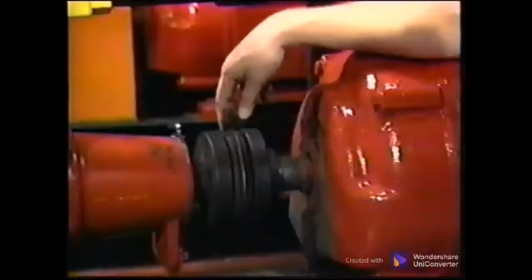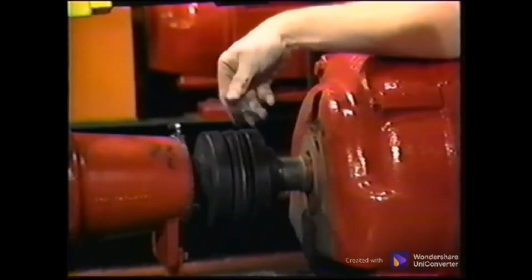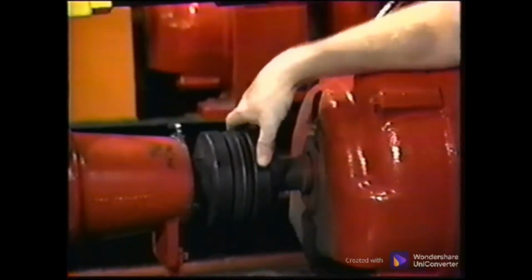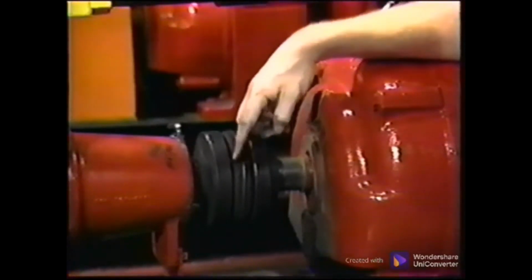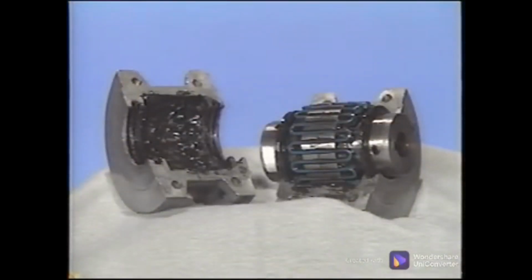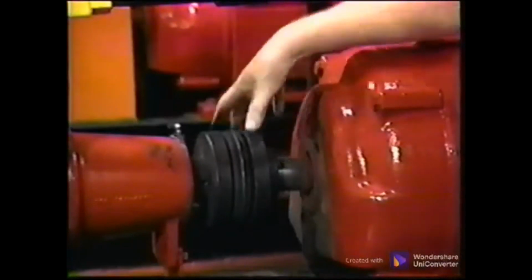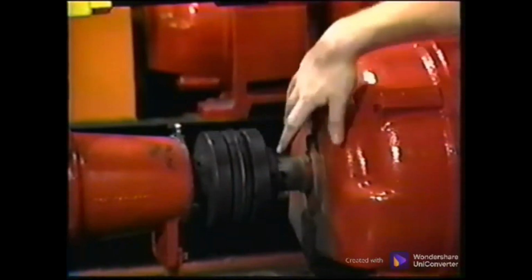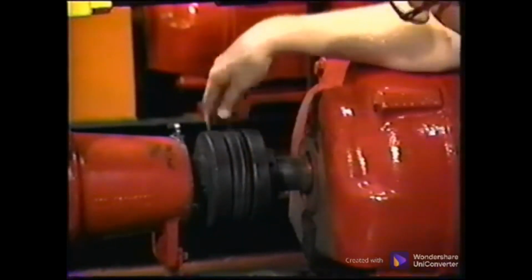If the coupling has a rubber insert, check for rubber powder because this is an indicator of the amount of misalignment, and a worn rubber insert can allow too much looseness in the coupling, accelerating the wear and increasing the vibration. On lubricated couplings, check for leaking grease as an indicator of wear or looseness. Check the keyway for wear and a loose key as an indicator of a loose coupling. Check the coupling for tightness and any play between coupling halves, including movement in the axial direction.